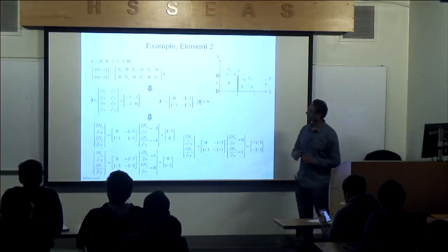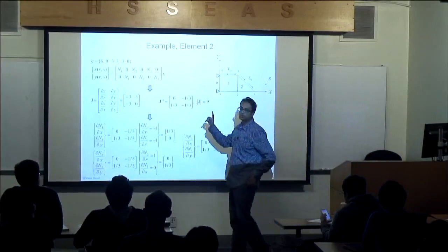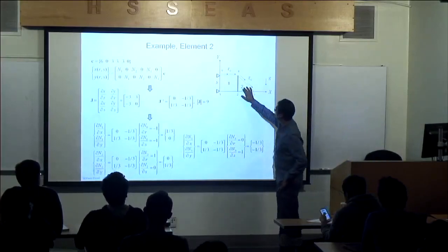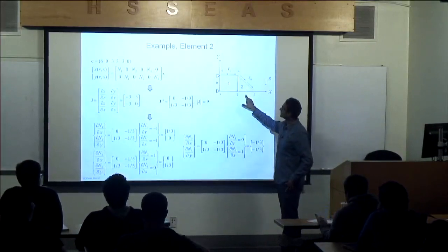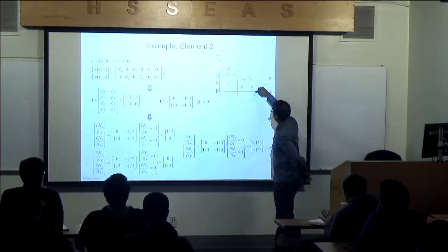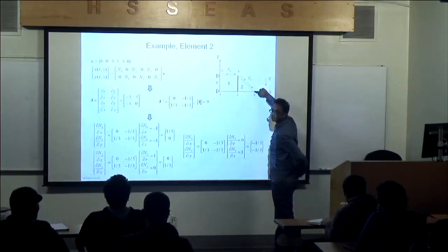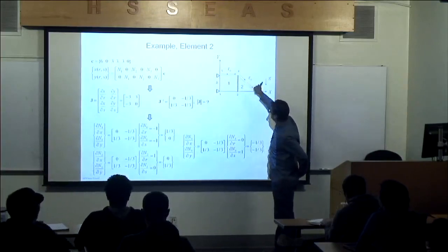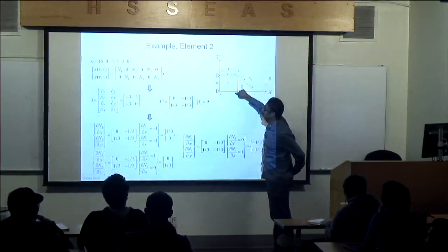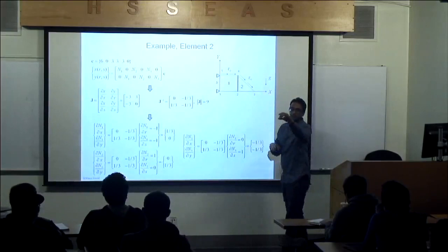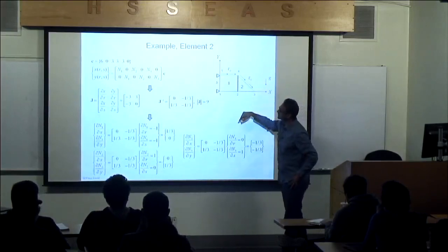All right. So now let's do the triangular element. Triangular element is this one here. I'm going to use the r, s coordinate system. And I've selected this to be the first node, second node, and third node. I didn't select this one to be the first node. I just did it this way for mapping purposes, so I can map that traction force a little bit easier.